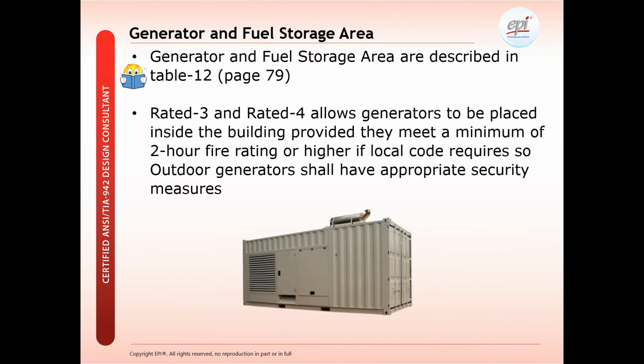On this slide here, it demonstrates the current requirements of the latest standard for generator and fuel storage areas. You need to follow the latest standard as opposed to previous standards, because the current standard now allows generators to be placed inside the building for both rated 3 and 4, provided they meet a minimum of 2 hours or higher if required by the local code.